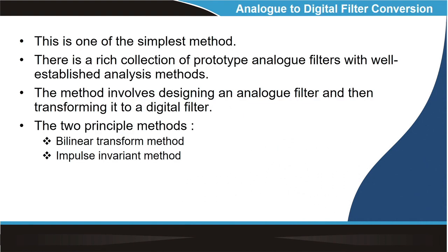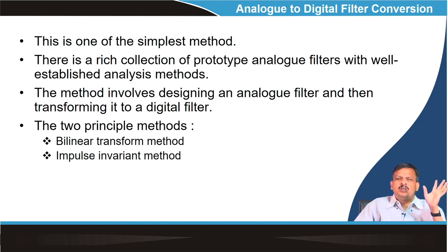This is the simplest method, because analog filter design methods were available long before the digital filter came out. So, the design methods of analog filters are well established. There are a lot of prototypes to design analog filters: Chebyshev, Butterworth, elliptical. All kinds of prototype filter design methods are available and already proven to be very good methods. So, in the analog filter design method of IIR filter design, what do we do?